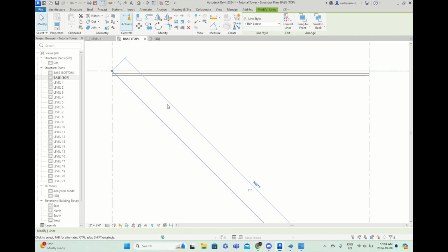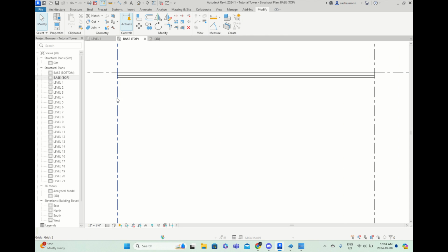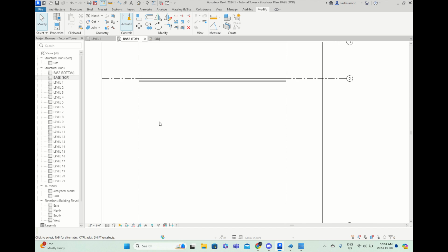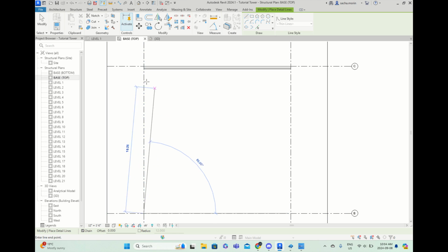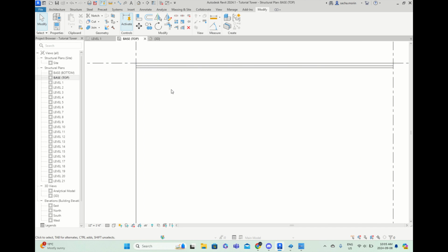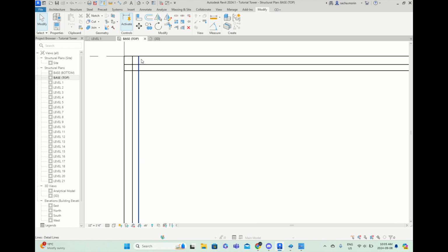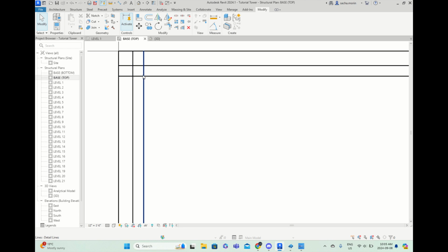So now let's do the same thing. I'll just delete this line for the side here on the left so that we can place that column. So again, design line, which is DL, left click, nice. Click escape to get my pointer back. Go back to the offset tool. We will offset by 1/8 to start. And then offset again by 3/32 of an inch. There we go. And this should be the center of our column, right where my mouse is.